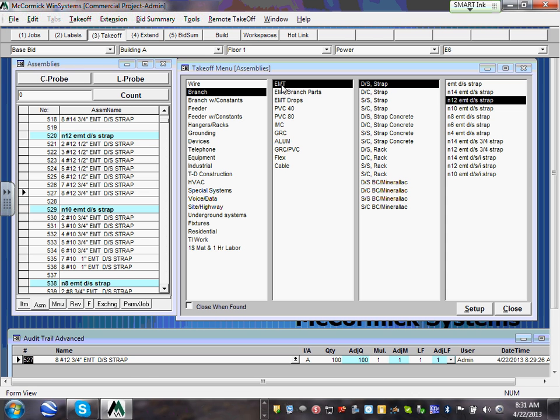So when you group them up, first you have to group your circuits in the ceiling in J boxes and shoot them all the way to the panel. Then inside the walls, we're going to be moving with MC cable from one receptacle to another, to the third, to the fourth, and pick them up. Take them all the way to a junction box in the ceiling, put them in 3/4 of an inch, and shoot them all the way to the panel. So that's the wiring method we're going to be using.